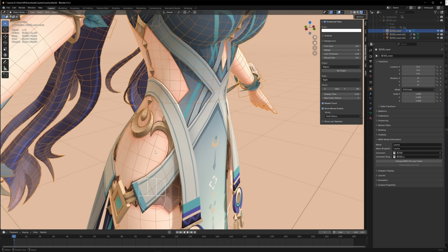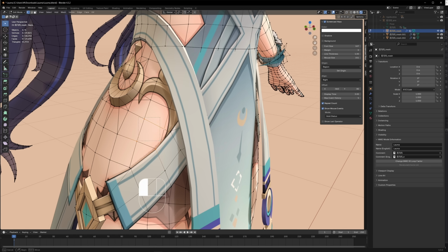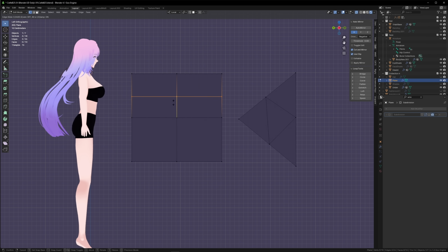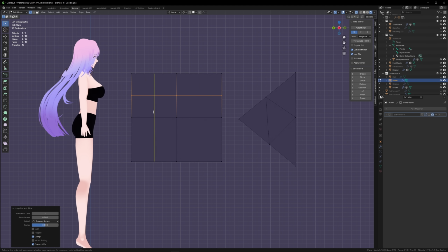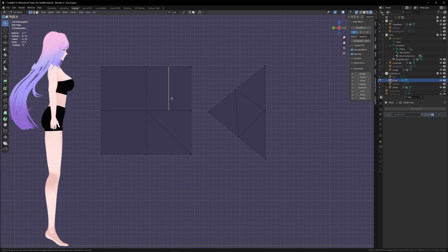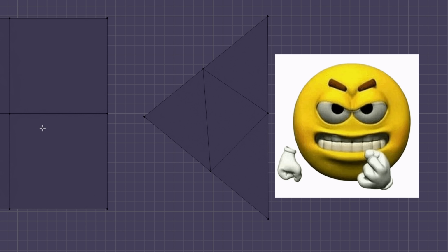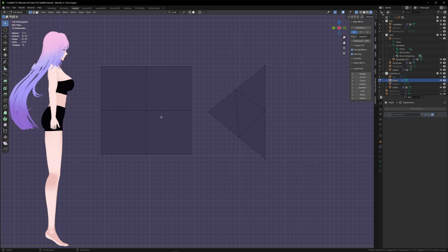This is because quads, or any face with 4 edges, are the optimal shape when it comes to modeling. Why? Because you can loop cut across them very cleanly, whereas triangles will block loop cuts like this. For some reason, people have oversimplified this to square always good and triangle always bad. But triangles are helpful. Necessary even. You just need to know when and where to use them.